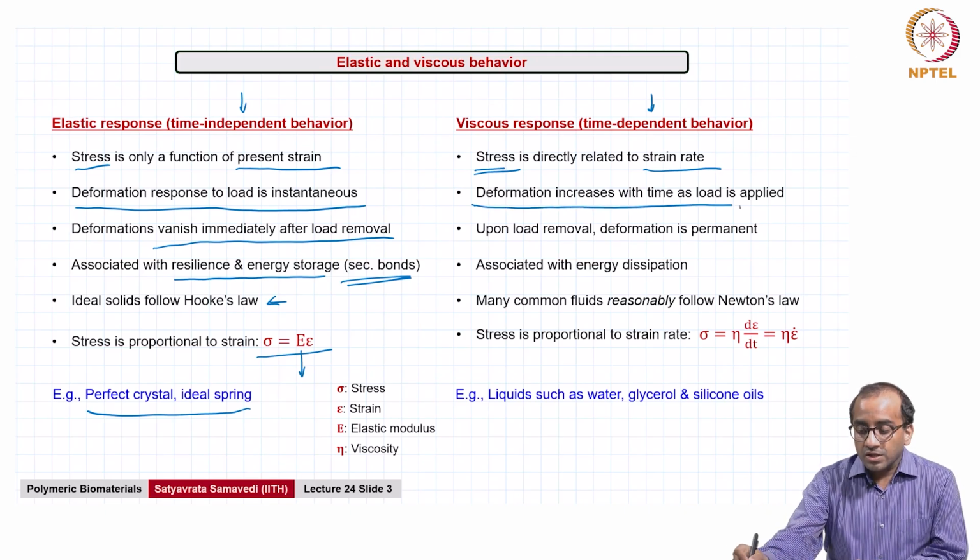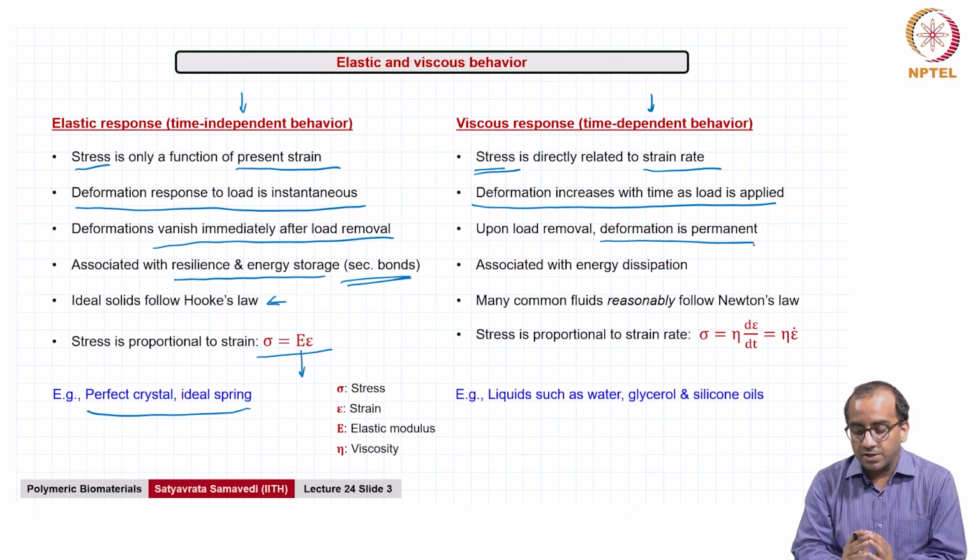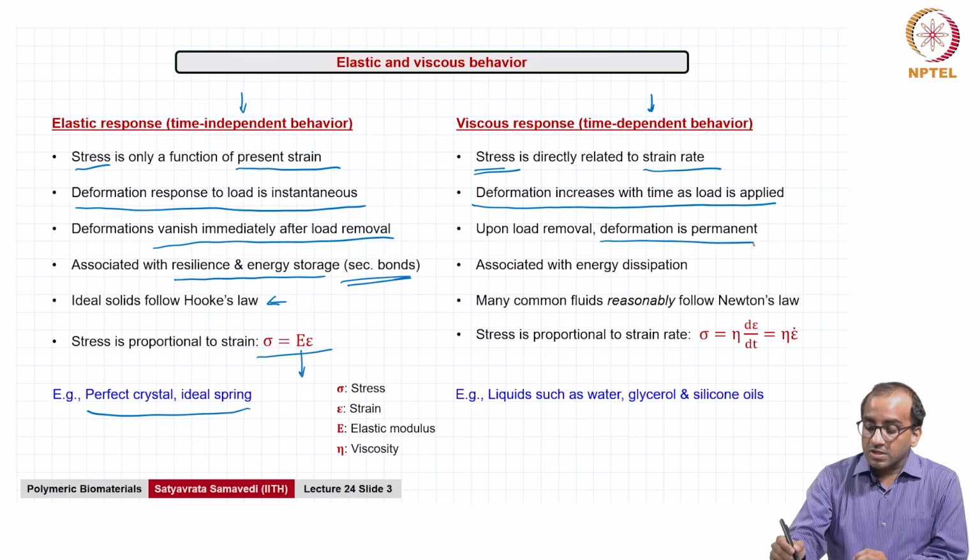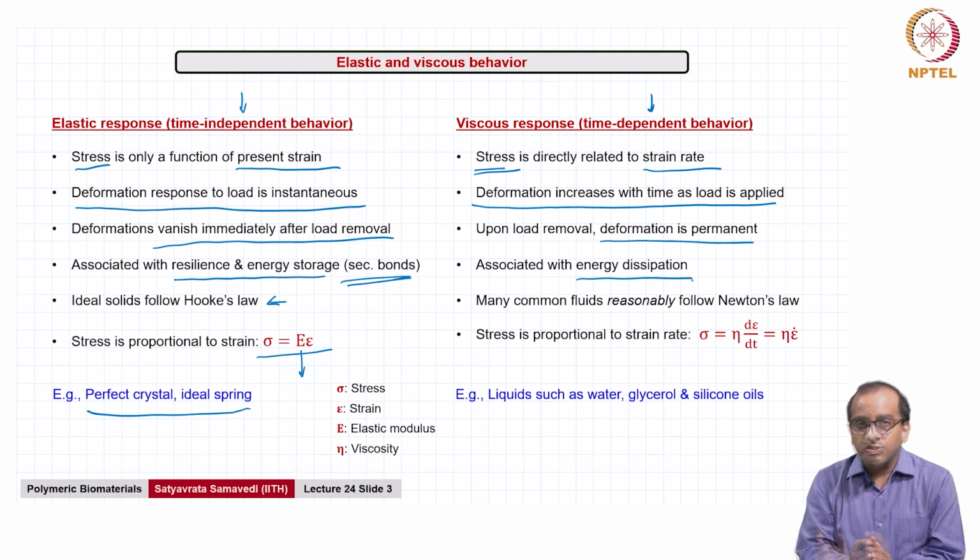And deformation for such fluids will increase with time as the load is applied, and once the load is removed, the material or the fluid is not going to go back to its original position or shape. The deformation that has occurred is permanent, and that is because this is associated with energy dissipation. Because purely viscous systems are associated with energy dissipation, once the load is removed, any deformation that has occurred is going to remain permanent.